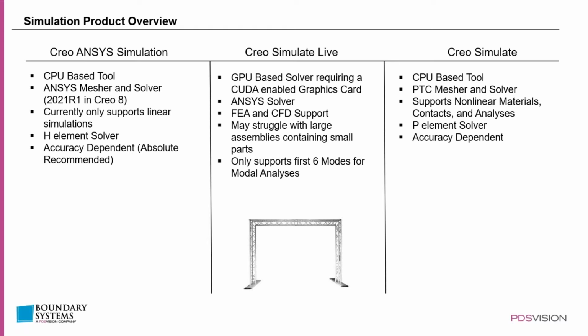Next, in the middle tab, we have Creo Simulation Live. This tool was introduced around Creo 5 timeline-wise, so a few years ago. But it is actually a GPU-based solver. So this requires you to have a CUDA-enabled graphics card. So there are some actual hardware requirements on the side of Creo Simulation Live. It is an ANSYS product that is incorporated into Creo Parametric, so it uses the ANSYS solver.